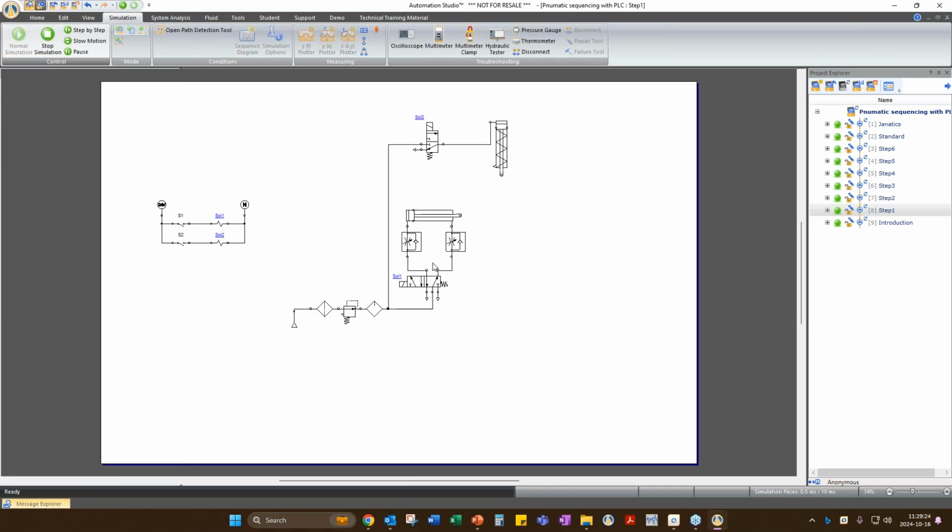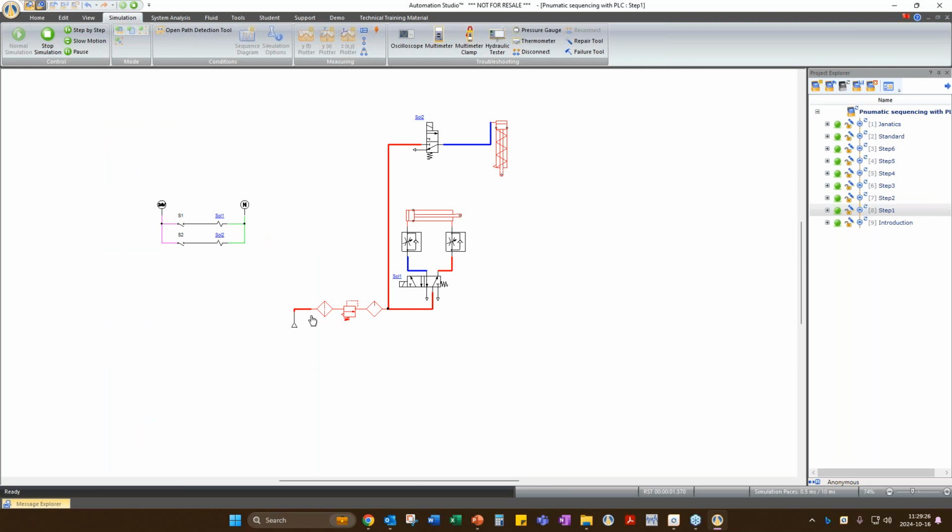So you'll find the circuit is getting started. You'll find this colorful display, so it is showing that there is some pressure present over here. Everywhere we have kept a threshold pressure value, so accordingly it will show you a color. If there is pressure more than some value, it will show a red color, or more than that, it will show a brown color also. For cavitation, it will show the pink color. So all the color options are available over here.